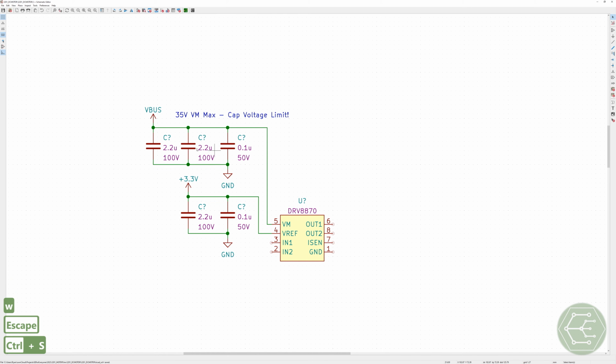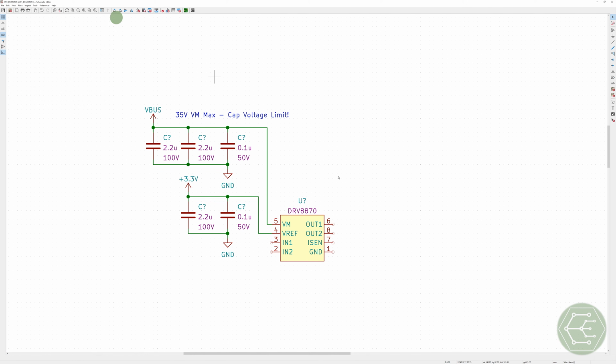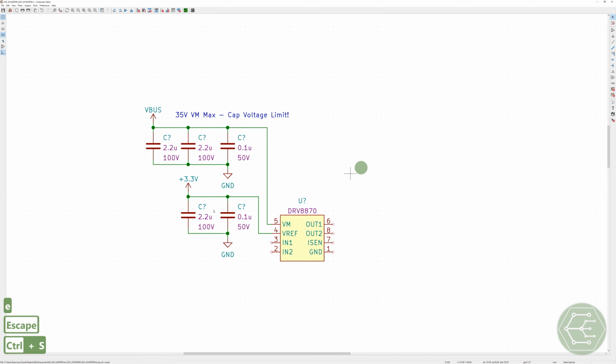Organizing things in libraries. And the nice thing about doing it like this is if I click in here, you can see well, I don't have a datasheet link for this. I guess it's a cap, but I have a manufacturer and a manufacturer part number that in theory, when you're not in a chip shortage, is an orderable part, which will make our BOM export really clean. And since I was consistent in my naming notation, you'll get a very nice BOM, which I'll show you in a second. Now, I might need to change that down the road for this Vref. That doesn't really matter. And in fact, I should probably add a series element here.